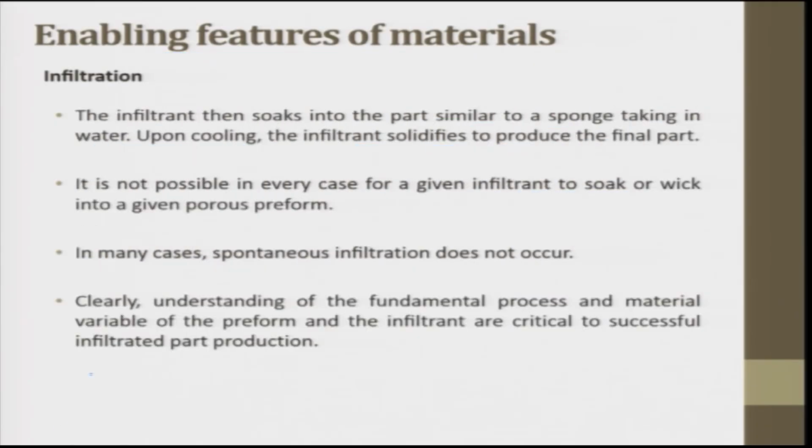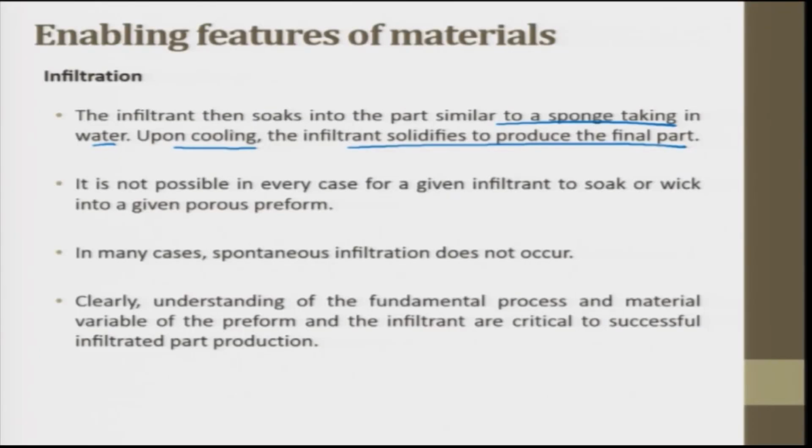So what happens? Infiltrant soaks into the part similar to a sponge taking in water. Upon cooling, infiltrant solidifies to produce the final part. Like we soak a sponge in water, and the sponge has a lot of pores in it. It looks like the sponge doesn't have a space, but it has a lot of pores in it and water is filled into that. And what if we wet the sponge completely and immediately we solidify that, we make ice of that water. So it is a similar kind of thing that is happening here. The infiltrant soaks the part in a similar way as a sponge taking in water. Upon cooling, the infiltrant solidifies to produce the final part.